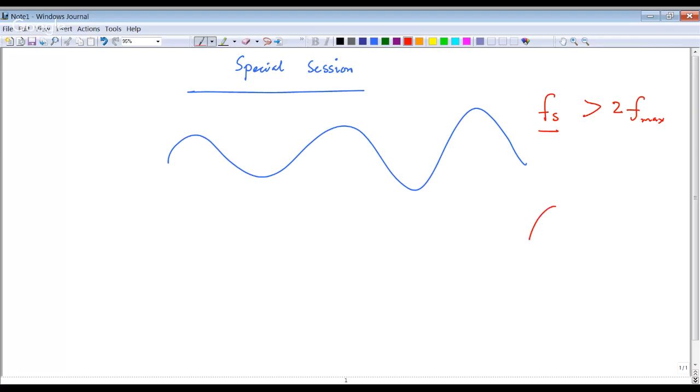points, for example, if you have a sine wave like this, if you sample at exactly this phase, then you'll sample here, you may sample here, you may sample at the 0 crossings. So if it is equality, then there is trouble, as you can see through this picture here. Therefore, we strictly restrict it to be greater than 2 times the maximum frequency.